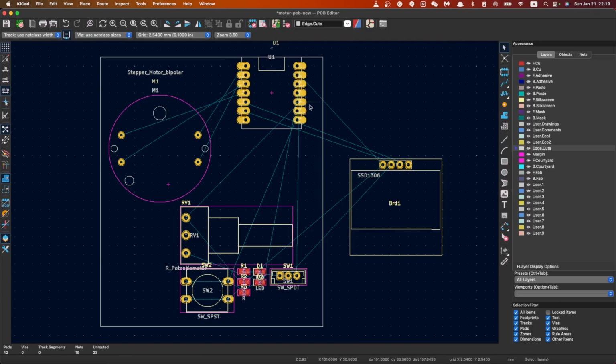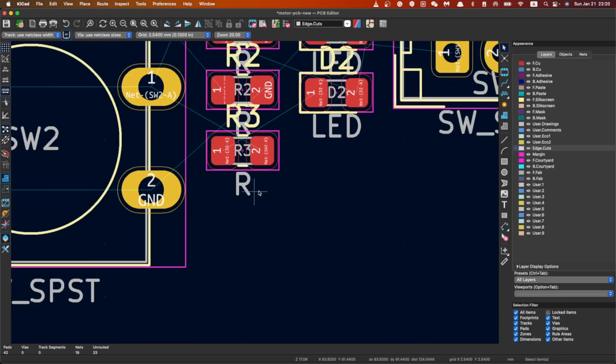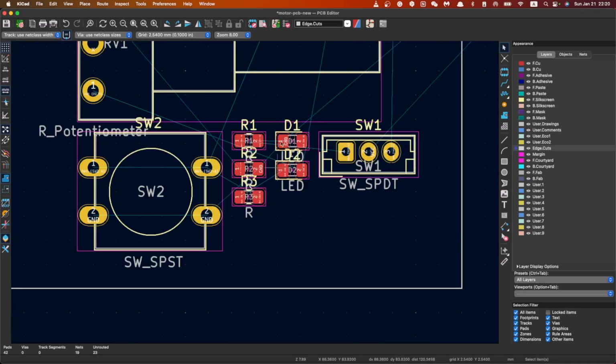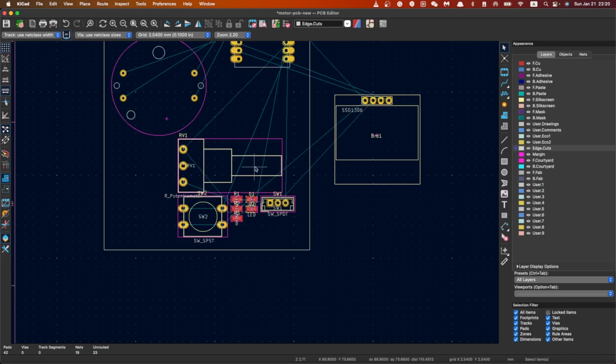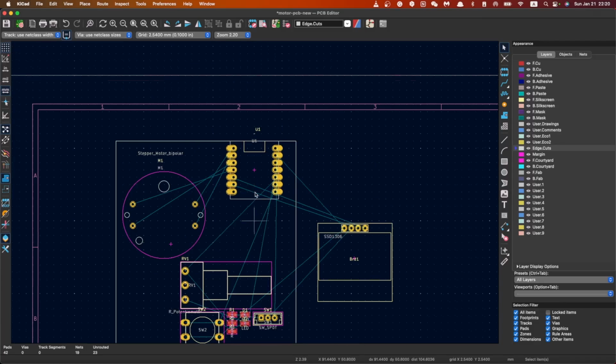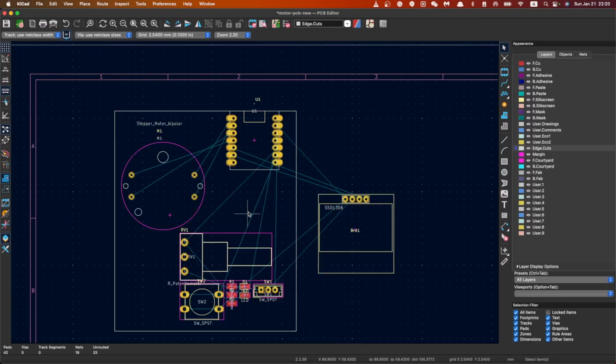But these red pins here, for the resistors and LEDs, are surface mount pins, which means these devices should be on the other side of the resistors and LEDs to make sure that their soldering pads are on the same side.